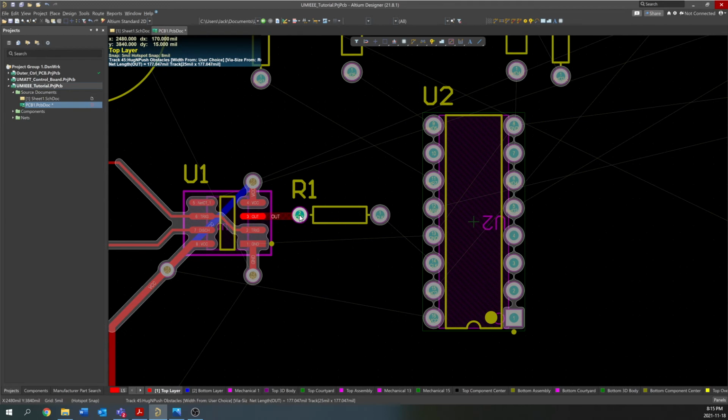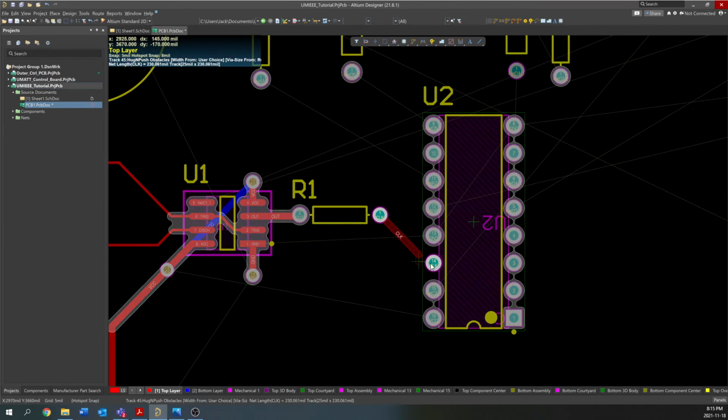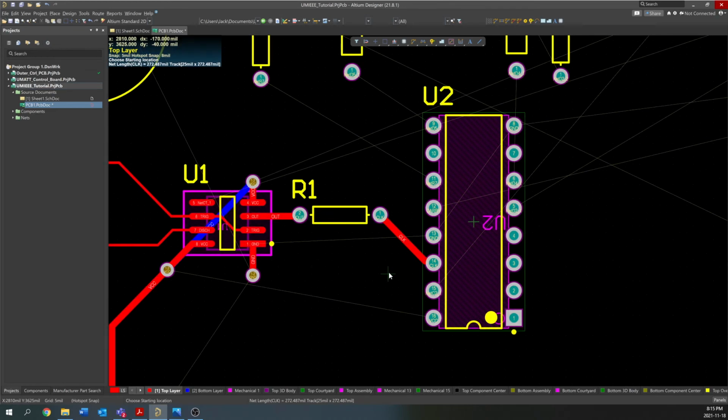And I'll just keep going with the 20 to 25 mil trace that I used here. Generally, larger trace width sizes are better. They have lower impedance, and yeah, that's the main rule. The main thing is lower impedance for your trace sizes. If you can use larger trace sizes, then definitely do that. Sometimes you can't because you have a lot of pins in a small area, and that's what you're limited by.